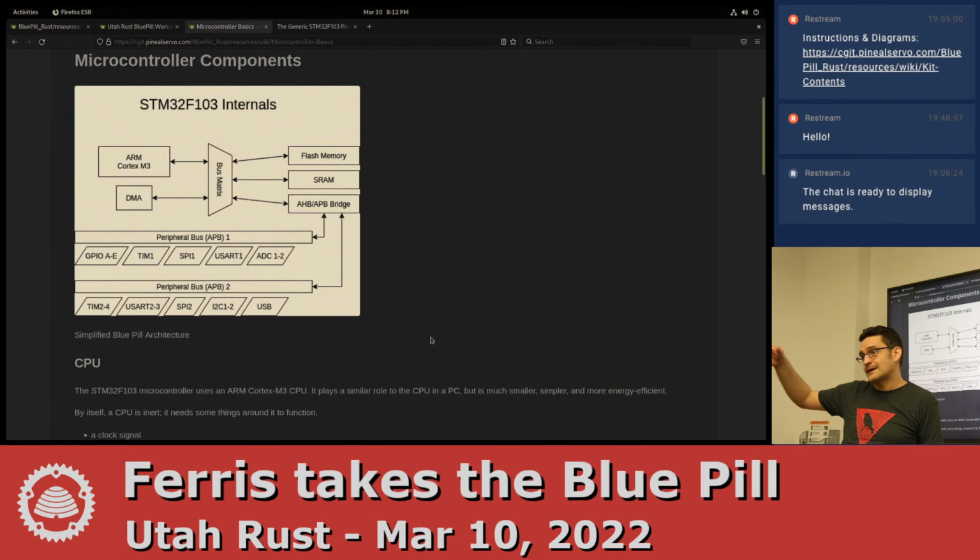You can also program that in advance and set it up to run a sequence of copies and loop back and continue doing it. It can be triggered by software or by a number of these peripherals down here. They can say, oh hey, I have some data, and they send a signal to the DMA controller. The DMA controller says, I'm ready to run my program, and it'll copy a bunch of stuff from the region of these peripherals into some buffer that you set aside.